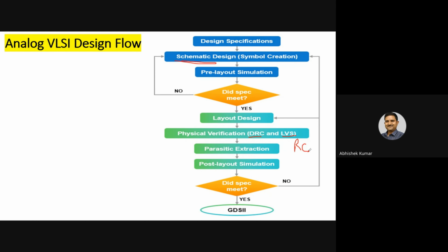Now think about your PCB. On the backside of a PCB, lots of copper wires run horizontally or vertically, crossing each other, and there is an air gap between them. Because of that, we have the epsilon value, so there must be some capacitance. How much unwanted capacitance can our circuit withstand? That is what we calculate as parasitics.